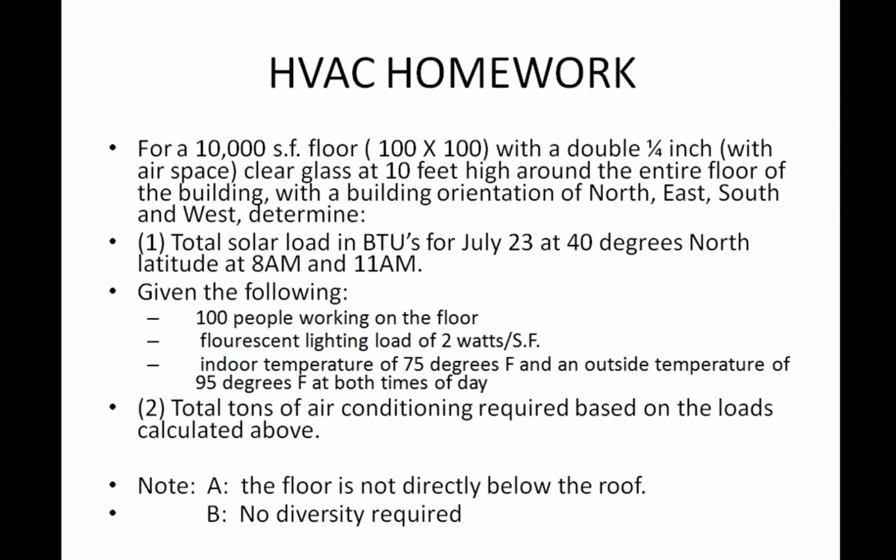Also note that this floor is just one of the many floors in the building. It's not the one directly below the roof. Because obviously if we were doing the one directly below the roof, we would have to consider the roof as a fifth surface, so it's not just 4 different sides. The roof would have some coefficient based on the type of roofing you're using, and would also have that difference in temperature, and we'd have to figure out what the heat loss or gain is through that as well. But for this example, let's just consider the 4 sides of the building on this floor. Okay, so hope that's clear.